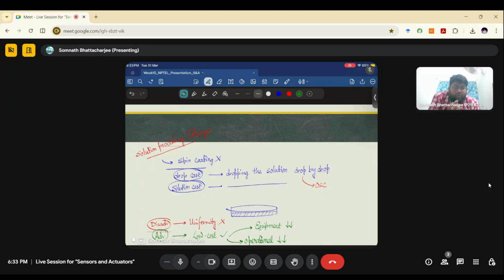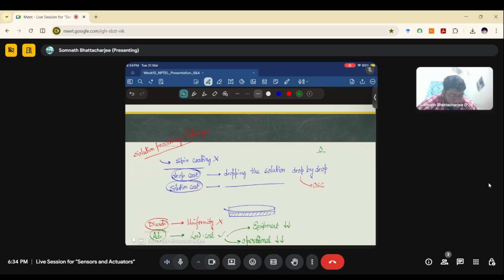But you need to know that a spin coater is like an 8-inch wafer size. Using an 8-inch wafer is fine, but beyond that, or let's say for 4-inch, the total size is 8-inch, but if your sample is very small, it will be more uniform. Because we are dropping the solution in the middle of the sample, there will be a gradual height change in these cases.